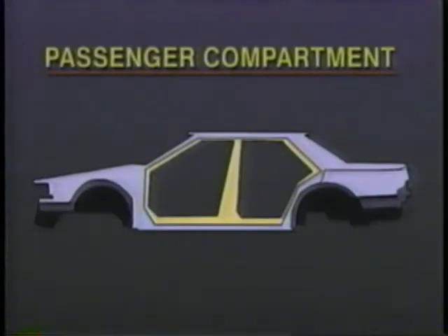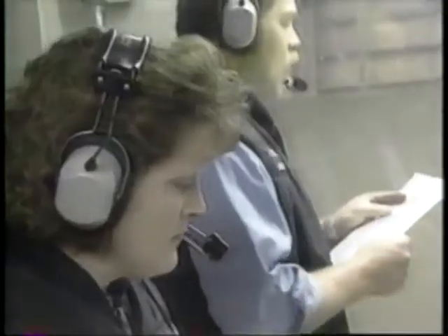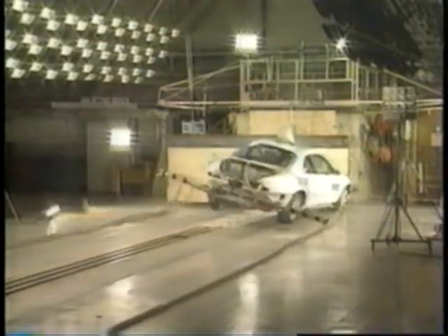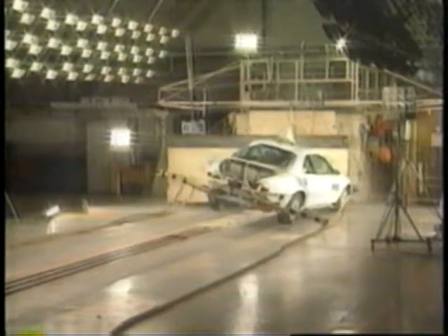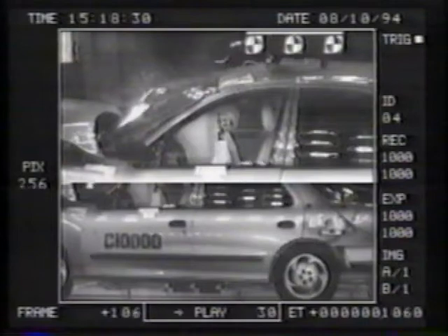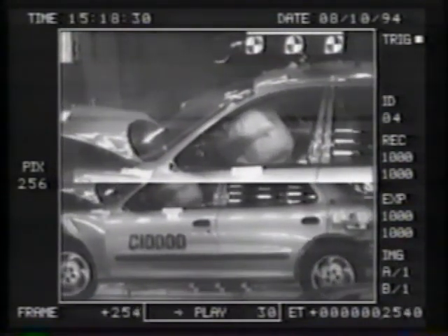Not padding like we found in the catcher's mitt, but steel, the car's body structures. The more these structures crush, the more crash energy they absorb. These crushable structures are designed in actual crash tests and on computers in order to predict how crash forces affect a vehicle. In a crash, deceleration forces start immediately, but vary as the crash progresses, so that the deceleration of the passenger compartment is at a constant rate, minimizing the force experienced by the passengers.